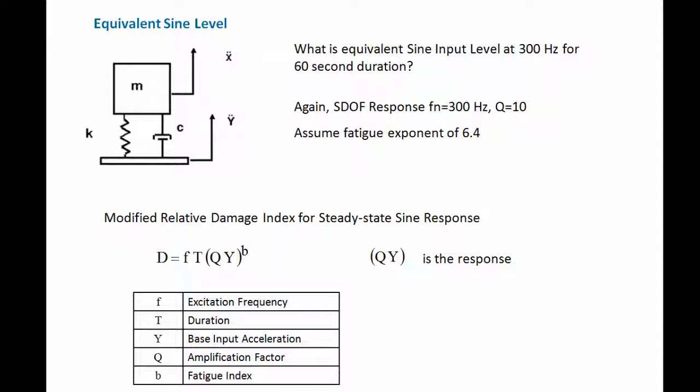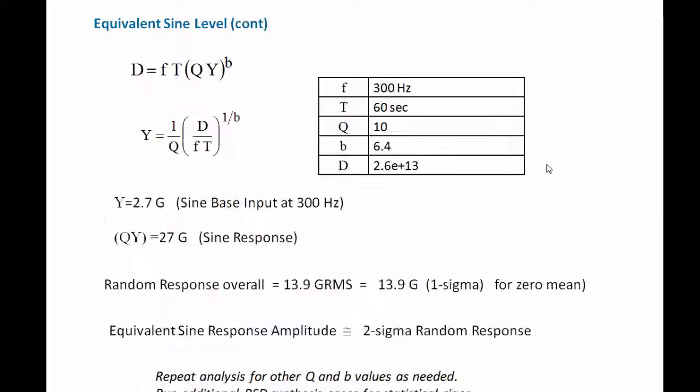Think about an ultimate stress failure, for example. But we're going to assume that our response levels are at least somewhat below the ultimate stress limit, whatever that might be for a spring mass system, and that our only failure mode of interest is fatigue. And for random vibration, usually it is fatigue that we're concerned about, with some exceptions.